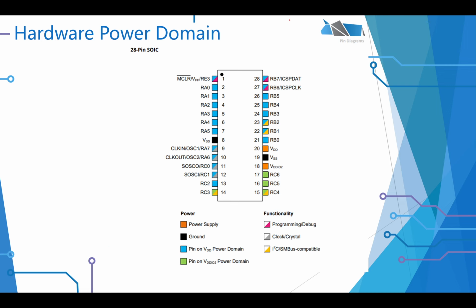Previously, let me just draw some lines. Purely for convenience, I had the SDA and clock on there. And then when I was doing one of the Microchip videos, which I have submitted to Microchip support, not the Microchip forum, which I'll speak about, I thought, hold on a minute. This domain stuff, let's recap what the domain is. This is a power domain, it's green, and I have to apply power to VDDIO2, and I've got 5 volts applied to that because that's the operating voltage that I want. And I had it connected to these two here, RC5 and RC4. I have TX on here, serial.